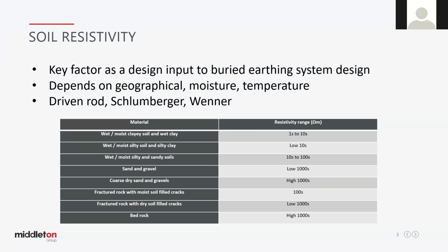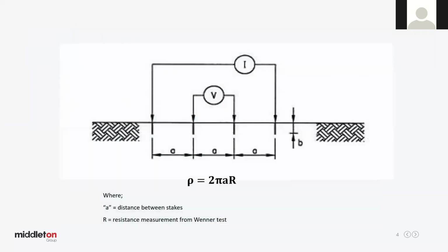And up in the mountains can be quite high. In fact, even an example we'll look at today, which was near the bay in Victoria, we had a couple of 100,000 ohm metres about 4 metres below the surface. So that gives you a bit of an idea of what you might be looking for, what you might expect.